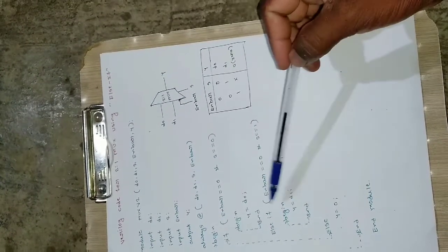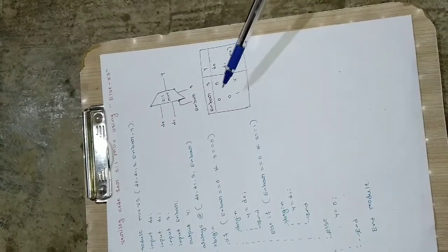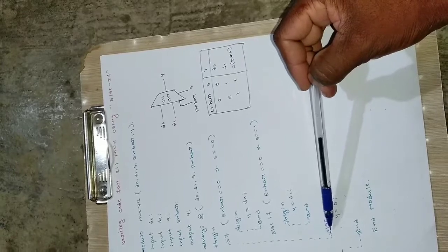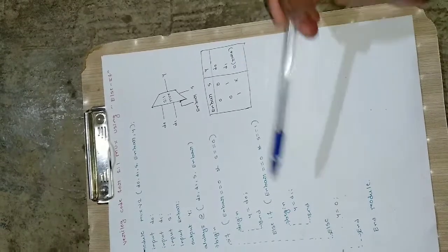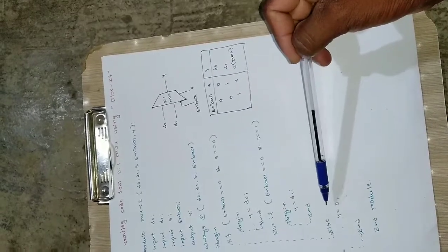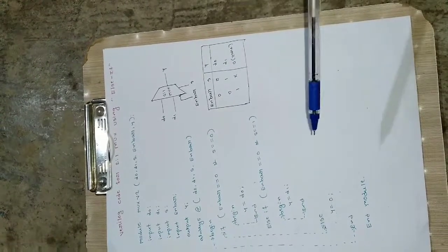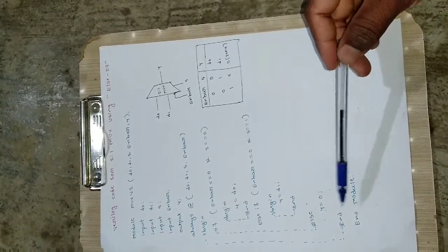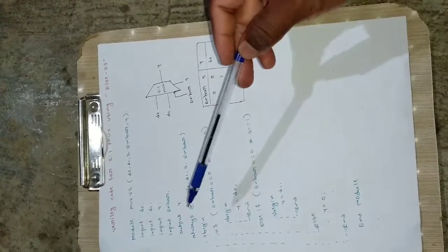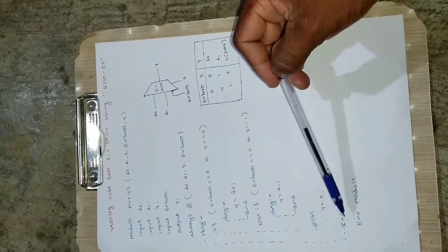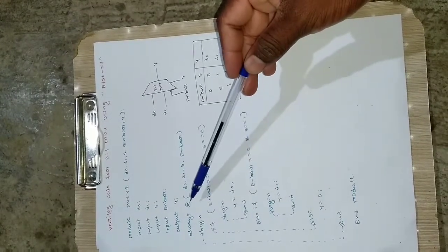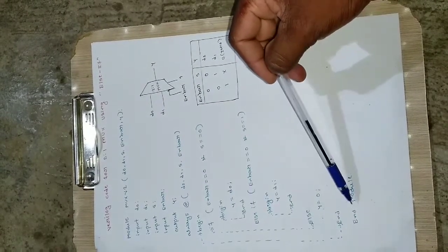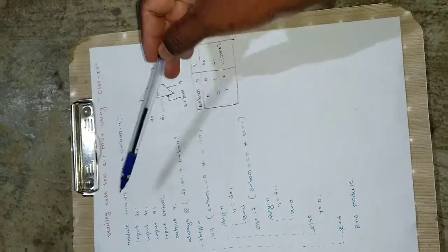Okay, so we have completed these two conditions here. So what will happen if enable bar value is equal to 1? For this I will be writing a direct else condition here. That means enable bar value is not equal to 0 for this condition. At that moment, as I already said, the output will be directly equal to 0. So Y will be assigned equal to 0 here. So this will be the end of the begin here. So this if is ended here. And this module will be ended here. So this begin and this end will be closing each other. Then endmodule means this MUX_v2 which we have opened here, it will end.